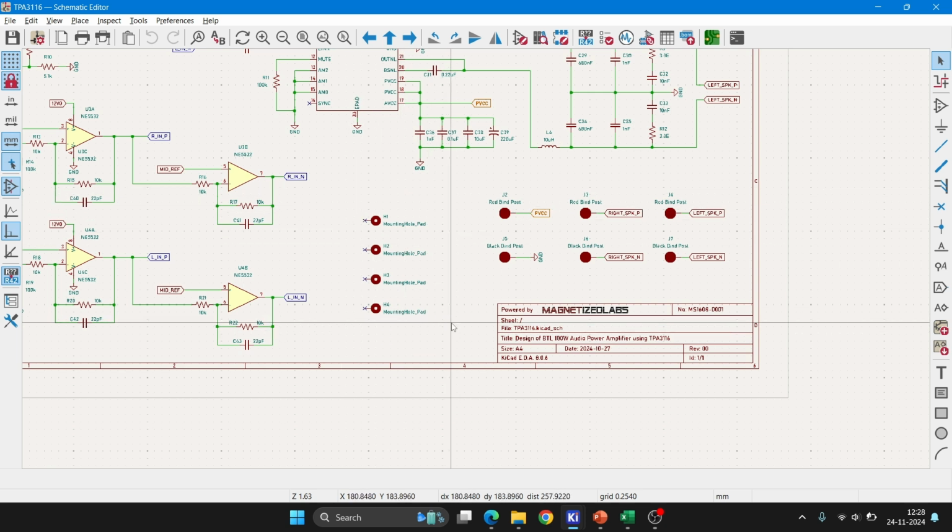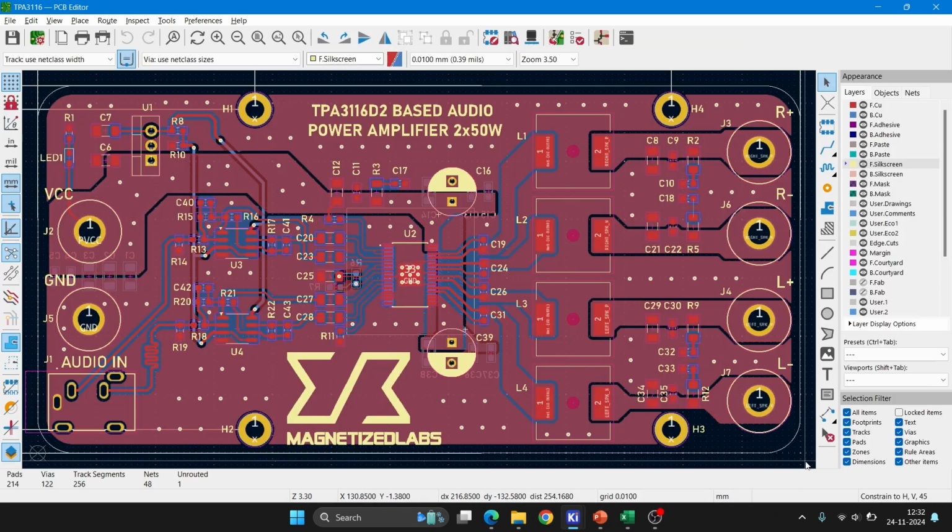Yeah, now we can go to the PCB. This is how the PCB will look. I will explain the placements. If you place the components very properly, that is equal to half the PCB done. So here I have kept the input connectors. I have kept labels to understand what each connector does, and then the ground pin connection here for the connector, and for audio input, I am using a 3.5 mm jack. So I am taking the audio signal from here.